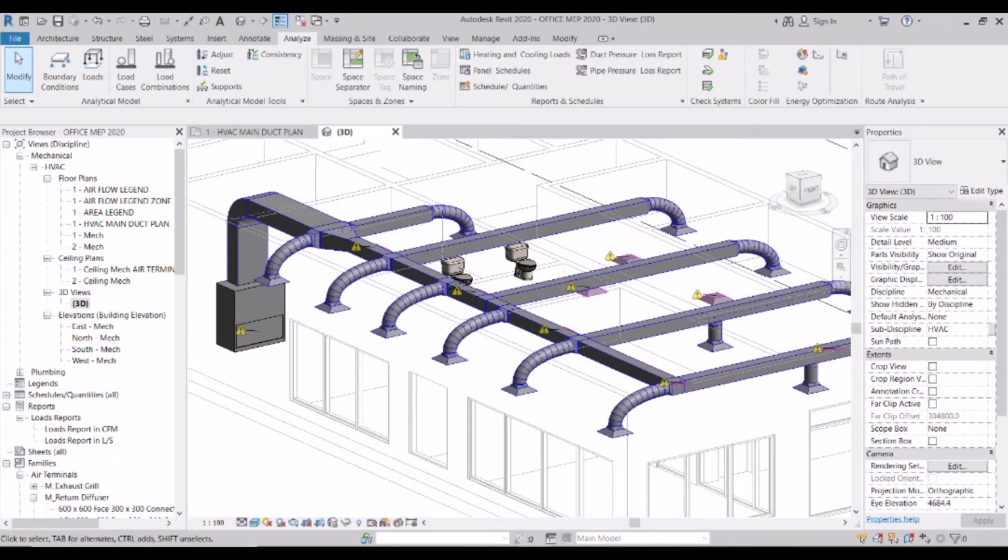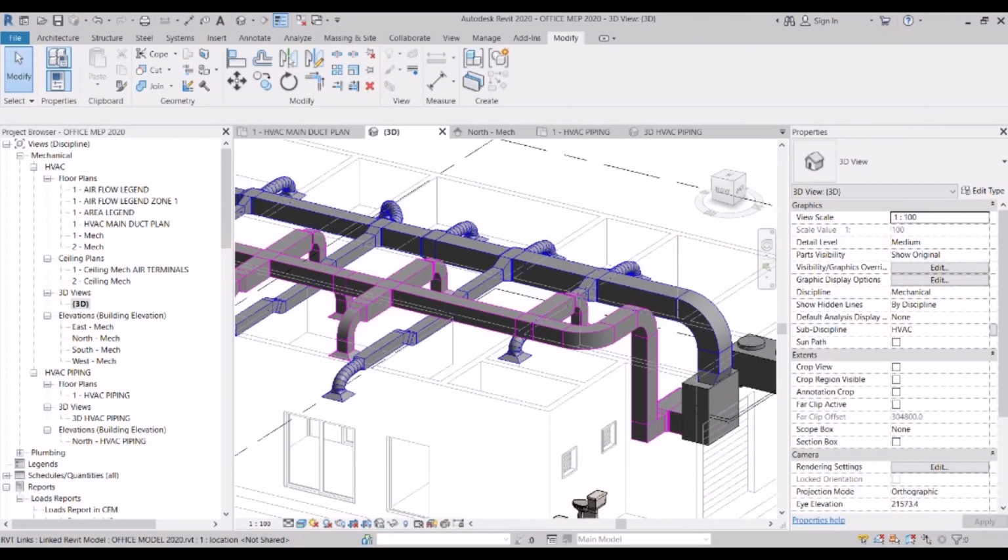If this room is for machines, it should be designed for certain conditions. If it is designed for humans, maybe for an office, we consider how many persons are inside. These persons contribute to the thermal heat, so we should design for a certain maximum number of persons.